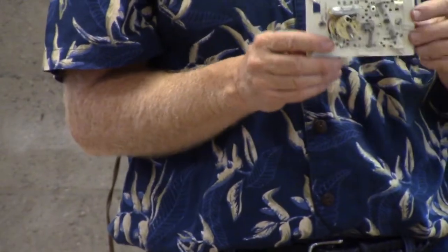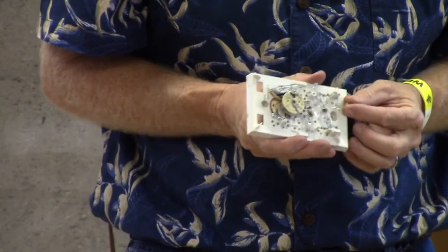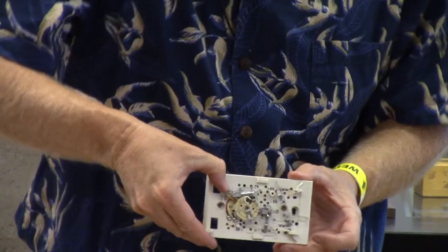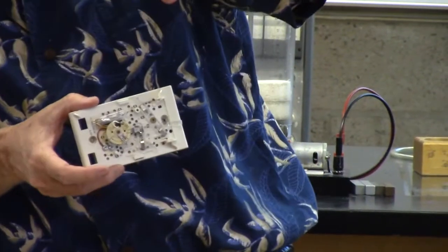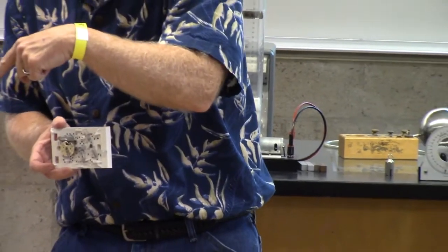And so this can be a switch in the sense that I can set my thermostat, and when it gets to a certain temperature in my house, let's say 65 Fahrenheit, it will move far enough over that the mercury will flow down, make two contacts of two pieces of metal, and that turns on the furnace.